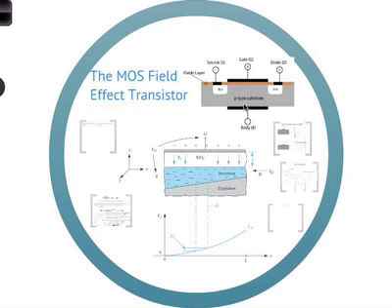Now look at the schematic here. This is what we will keep in mind. The coordinates are x along the channel length, z is out of the plane of the screen, and y is perpendicular to the gate electrode. So we have a metal gate electrode, silicon dioxide insulator, the inversion channel, the depletion region, and the substrate. You have the drain on this side, source on this side. Current flows, of course, from source to drain. Electrons flow from drain to source. So far so good.